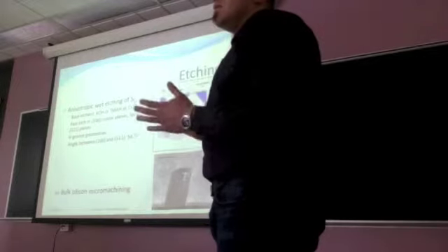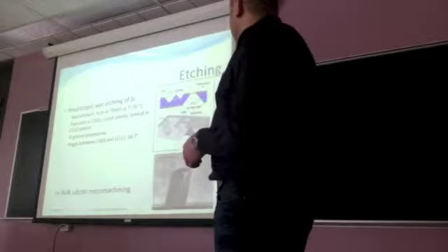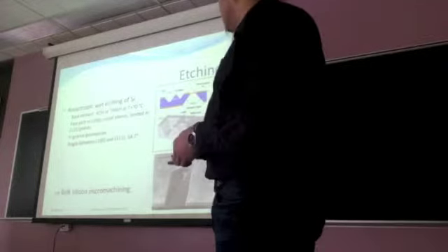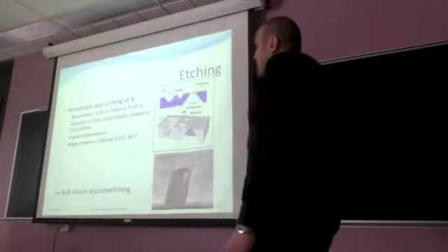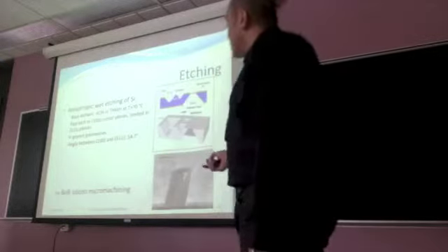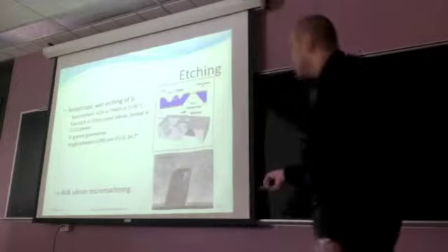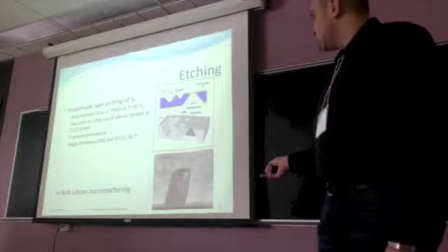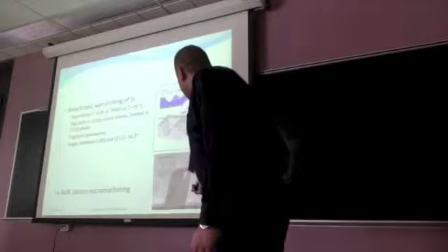The etch depth of silicon depends on the opening. So when you have a large opening, like here, you can get a silicon membrane. And the angle between 100 and 111 planes is 54.7 degrees. So this anisotropic wet etching can be used to do micromachining of bulk silicon. And on this picture, you can see an example, a tip for an atomic force microscope. I don't know if it's clear, but we can see the different sides corresponding to the crystal orientation of silicon.